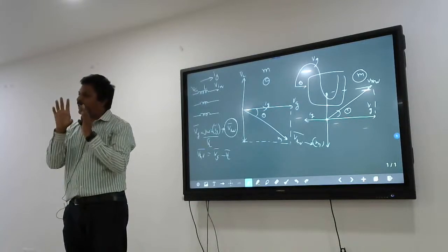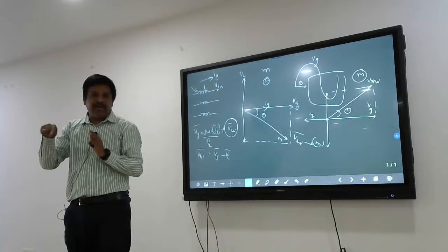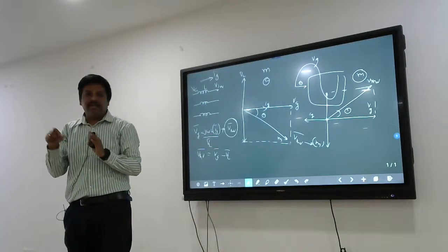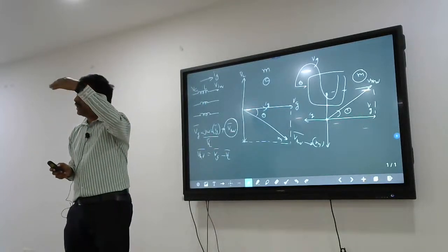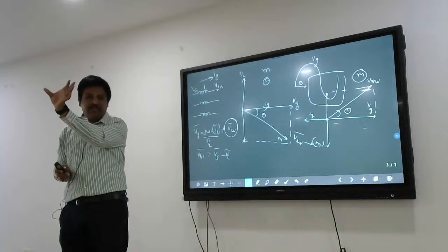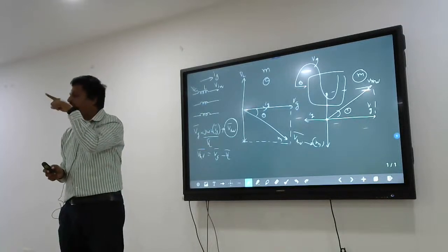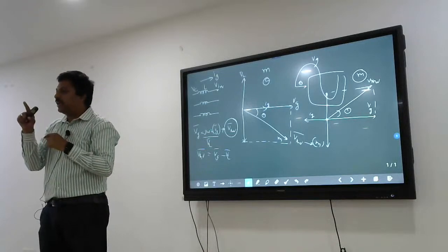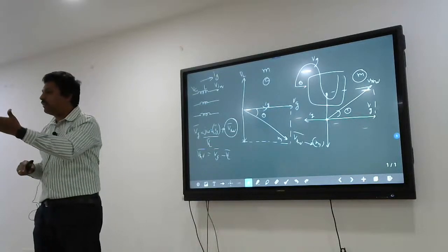You know that in a simple inverter, if you apply the sine PWM technique, why we apply sine PWM is that if you give a sine reference and compare it for switching, we will get a sine waveform. If you give a trapezoidal waveform and compare it with the high frequency triangular, you get a trapezoidal waveform.